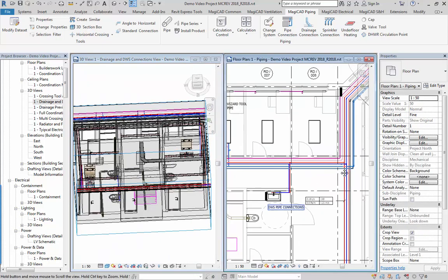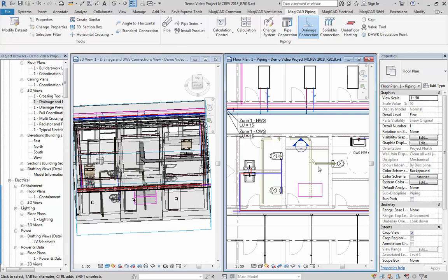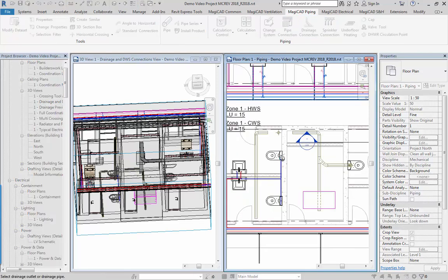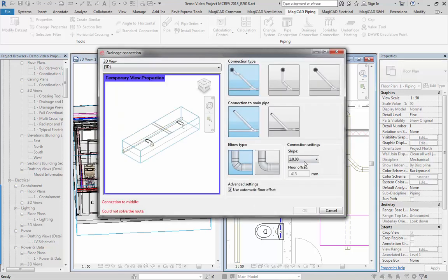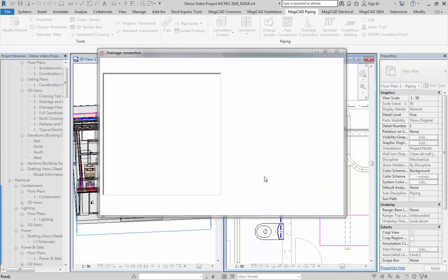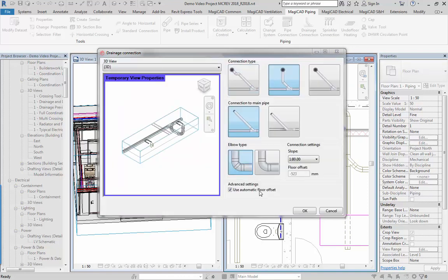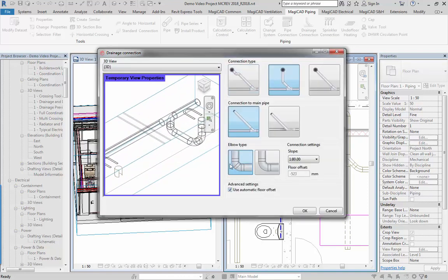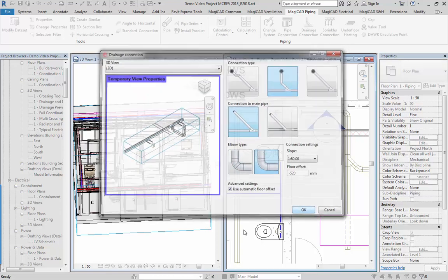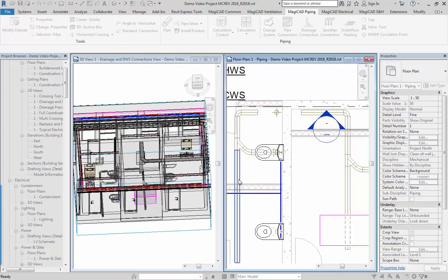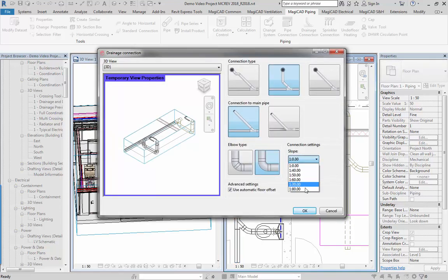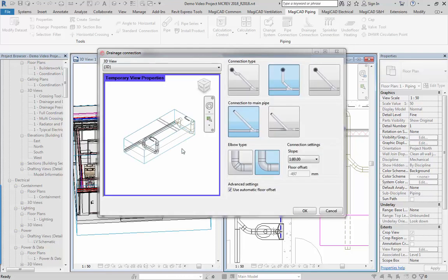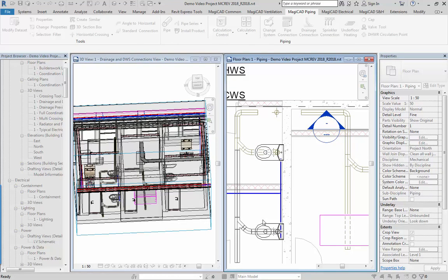And then finally, just using that drainage connection tool again, if I want to connect up some, say, toilets to this sloping pipe work, similar kind of idea. We can choose the gradient, choose the connection type in there, and then choose whether it's 45s or an 88 or 90 degree elbow. Press OK, and then just repeat, and then click into there. And what it'll do will obviously put the preset gradient of pipe work onto that connection at the same time onto the other gradient.